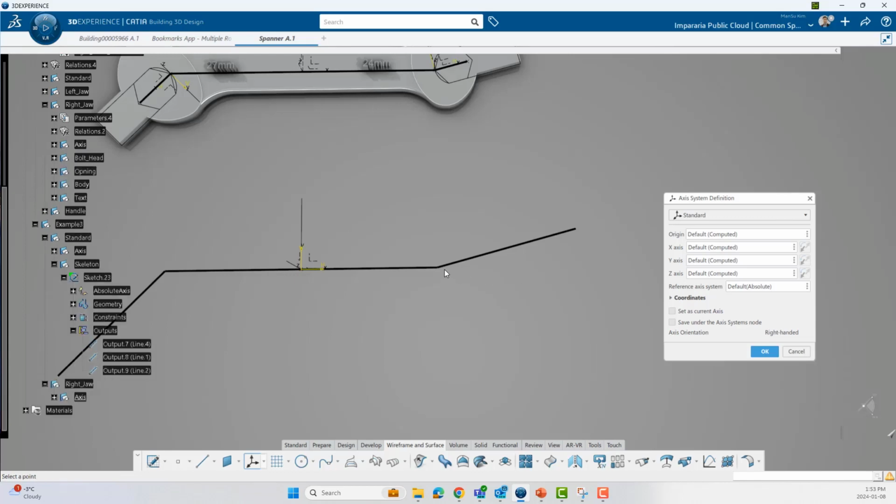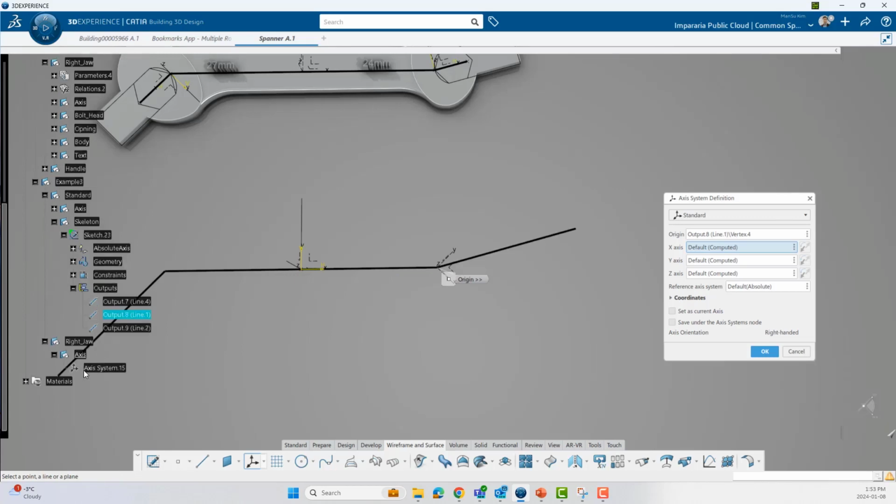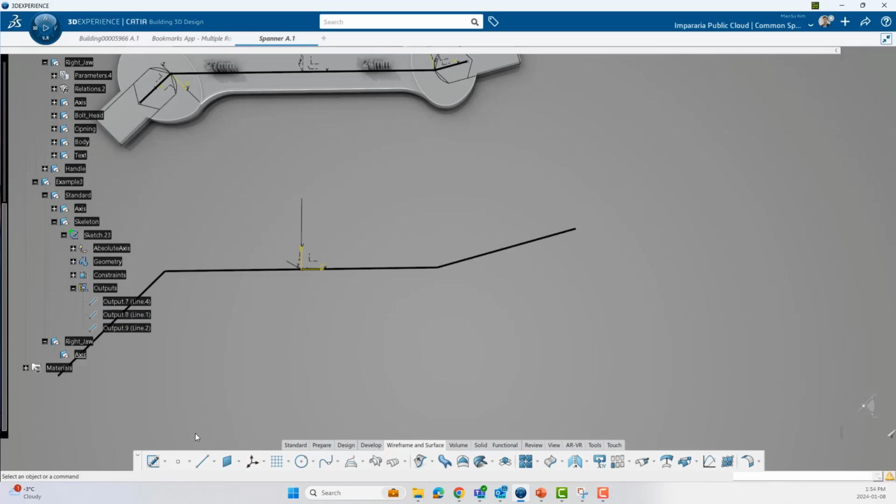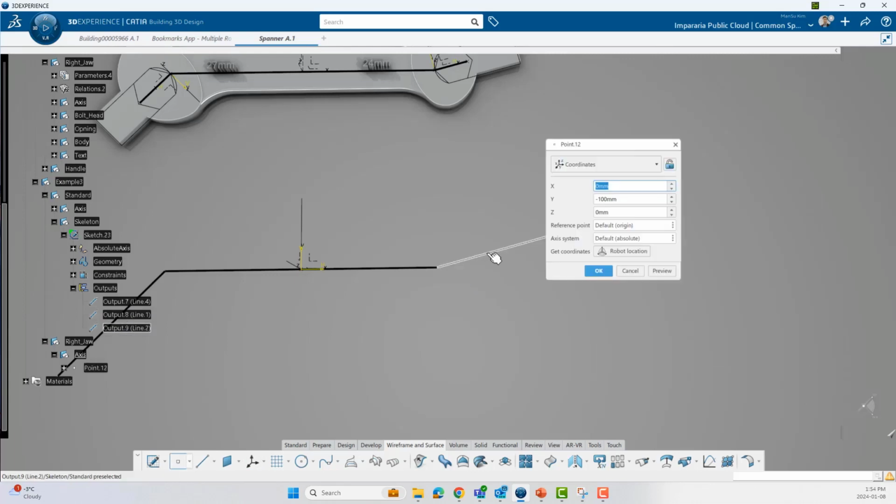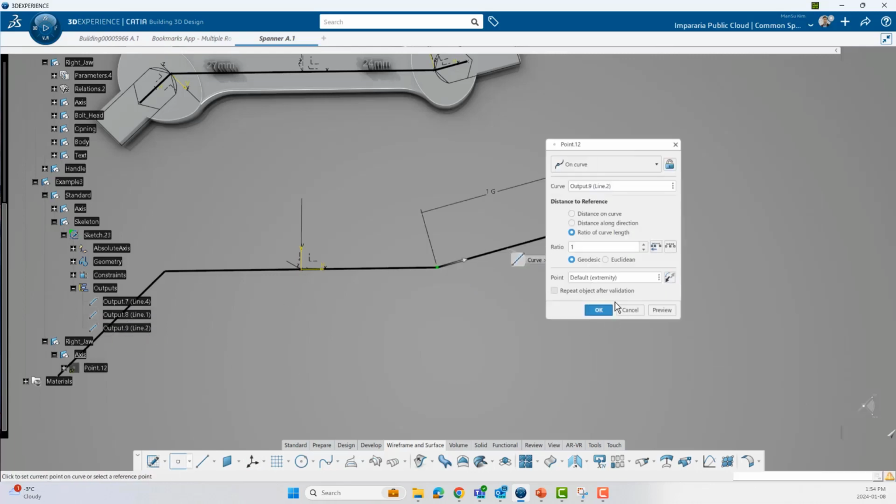We're creating the point. So you can click here, but we don't want to click the vertex of the line. So instead of that, we can create the point. Why are we doing that? Because if you click the vertex, actually you are out of control. You cannot control the location of the point. It really relies on the parent's side. So instead of that, we're creating a point.